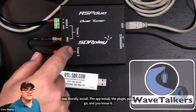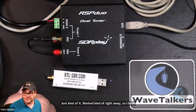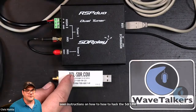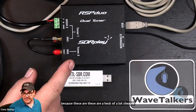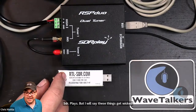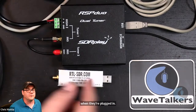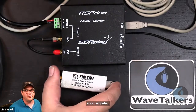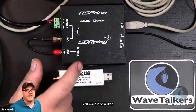So I have seen instructions on how to hack the SDR Uno software so you can use it with an RTL SDR dongle, because these are a heck of a lot cheaper than the SDR Plays. But I will say these things get wicked hot when they're plugged in. So you definitely don't want it plugged in directly into your computer. You want it on a little USB tail if you can, so you can get a little more airflow around this thing, because it gets just smoking hot and it does burn a lot of battery power.